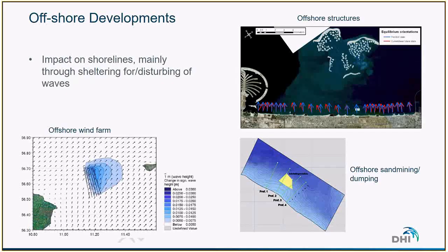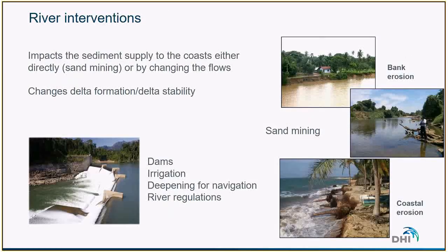Finally, the offshore sand mining or dumping of sediment can have an impact as well, because it directly affects the bathymetry, and as a consequence, this can have an influence on the forcing, currents and waves close to the shore, in the coastal zone.